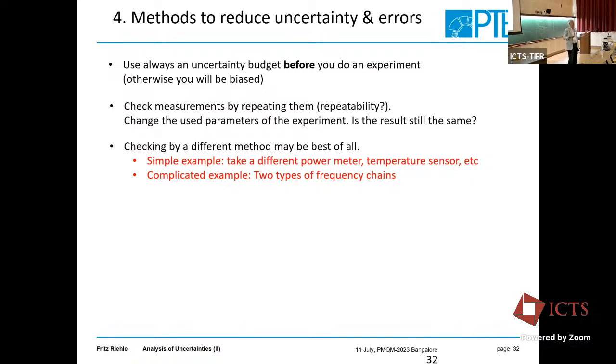Calibrate the power meters. It's a service you can get from a National Metrology Institute, but you can also get it from a company. So if you have a calibrated power meter, then use secondary standards, and every 2 years or so, redo the measurements. That is sort of a quality management system you have in the laboratory.